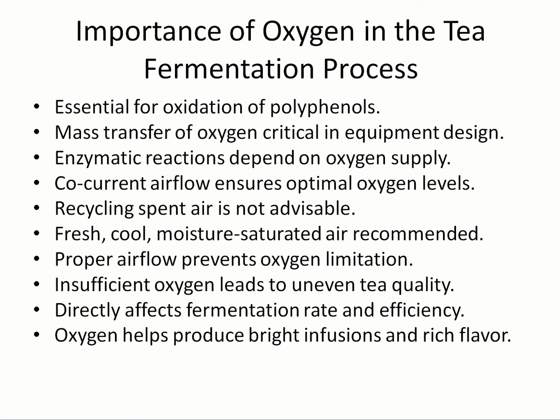Importance of oxygen in the tea fermentation process. Oxygen is essential for oxidation of polyphenols. Mass transfer of oxygen is critical in equipment design, and enzymatic reactions depend on oxygen supply. Co-current airflow ensures optimal oxygen levels. Recycling spent air is not advisable.